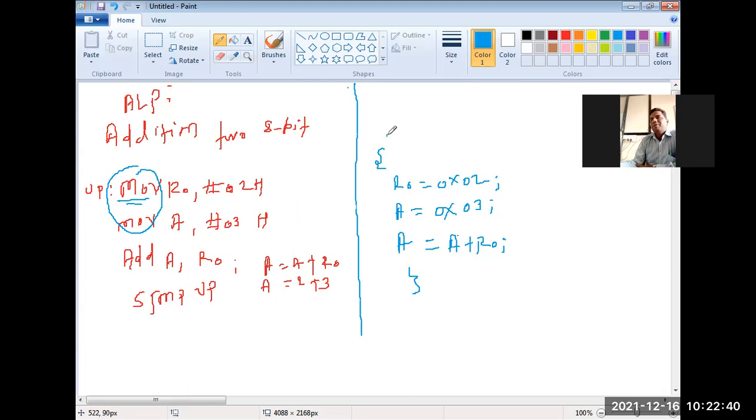But I want to keep it in a complete loop. So I'll use while, and put 1, which indicates the true condition. Keeping the while loop depends upon the value defined. If I write x greater than 10, unless I'm creating an x variable and it is not increasing step by step, it will keep in the loop. Otherwise, I'm putting here while (1), which indicates the true value.